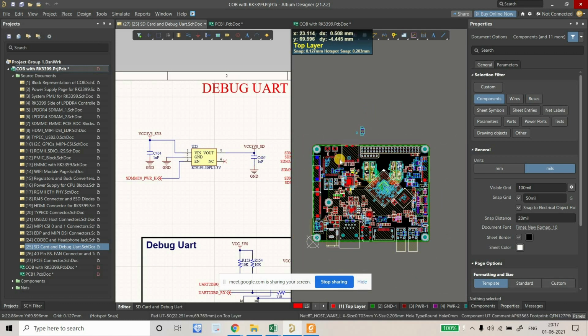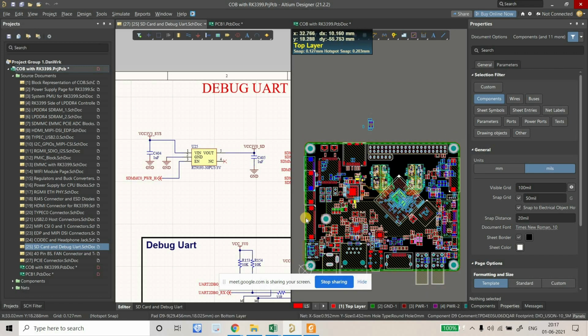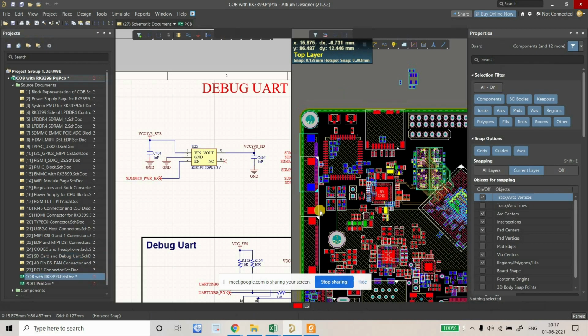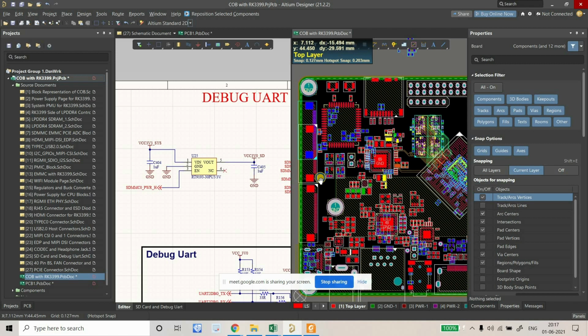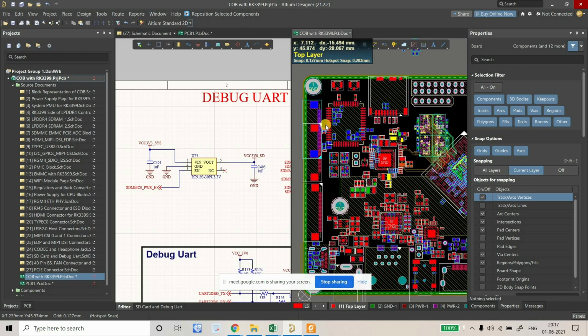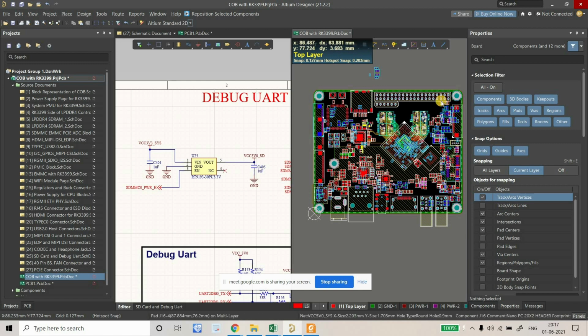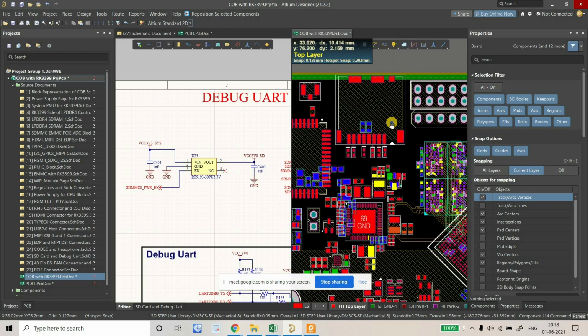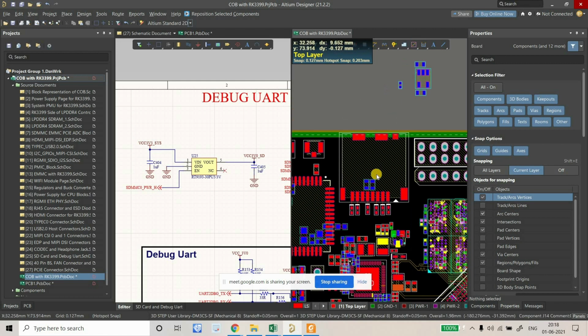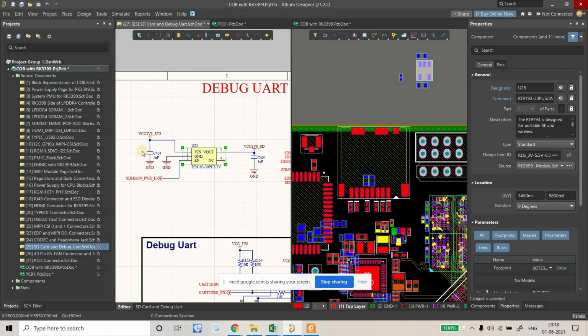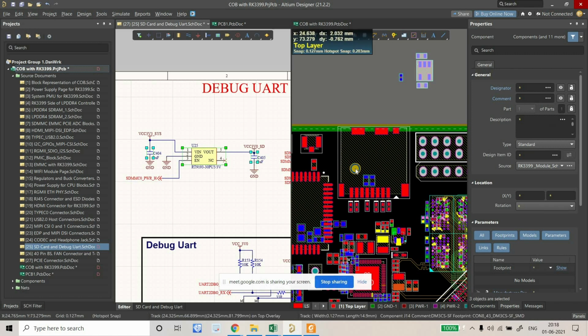So from that we can understand that all these PMIC, all the regulators, all these MIPI connectors are powered through 3v3. That means there will be a thick copper, or a section of the power plane, which will be around like this. From that idea you can also understand this is the right position to place these regulators, whose only purpose is to supply the SD card. So select it and just place that quickly.